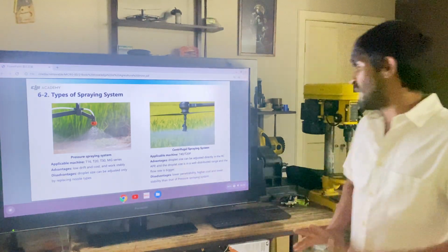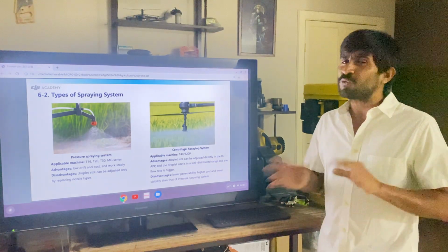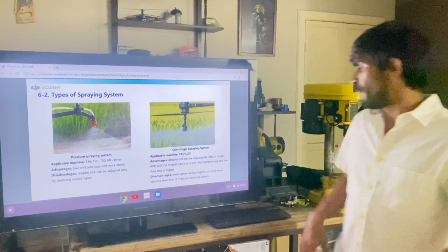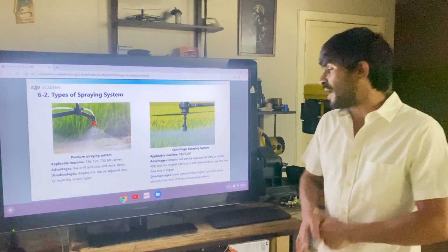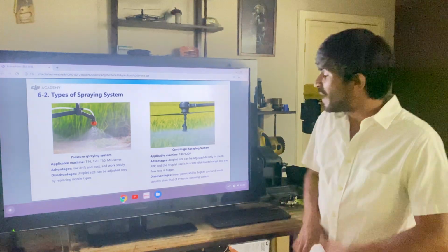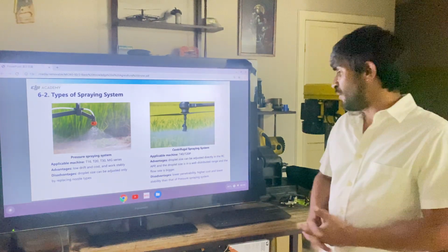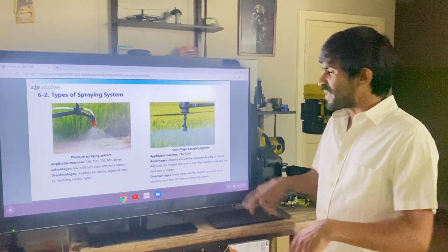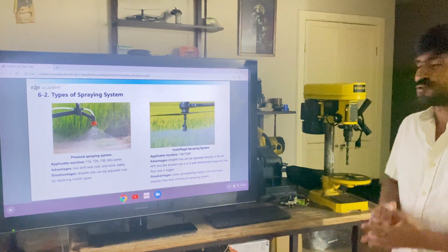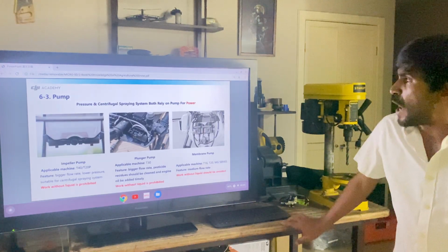It has a little bit lower penetrability, but if you use the right droplet size, going a little bit up in droplet size, you can achieve normal penetrability. It does have a higher maintenance cost. You have to be careful because you have a motor here, and you have to make sure the seal doesn't get corroded. But you get a much better spraying distribution.